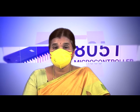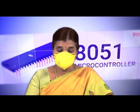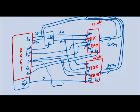For the chip select signal, how are we generating it? The unused address lines will be used to generate the CS bar signals. For the ROM signal, A15 is connected via an inverter. For the RAM signal only 13 lines are used, so the two signals 14 and 15 are not used. I will connect the 13, 14 signals with one NAND gate, and the NAND gate is connected to the CS bar signal.